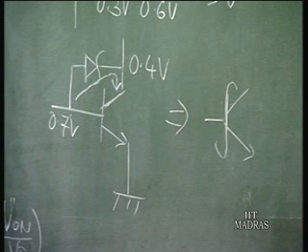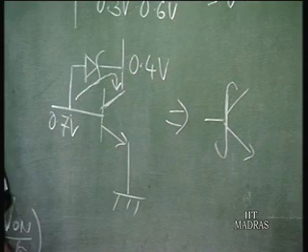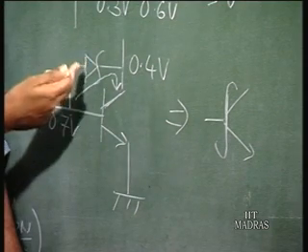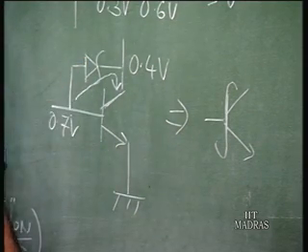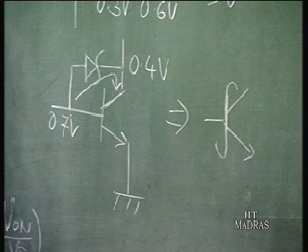This transistor is not going to go to saturation, because the Schottky diode will start conducting when the transistor goes to the edge of saturation, and obviously this transistor will not have the storage delay component, which is going to make it a faster device.